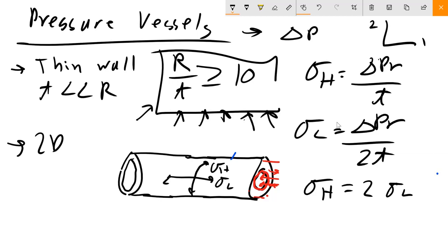This tells us a lot about how this material should fracture if there are no defects or other stress concentrators in our material. Materials always fail where stress is the highest. They want to release this built up strain energy as quickly and easily as possible. So materials will fracture, generally speaking, where the stress is the highest, along the path of least resistance. So if I apply a large stress, if I stretch my material, you can imagine stretching it out here and here, how should this cylinder fracture?